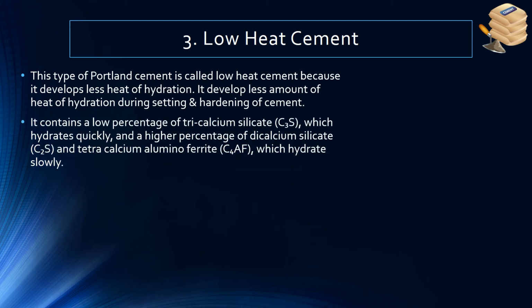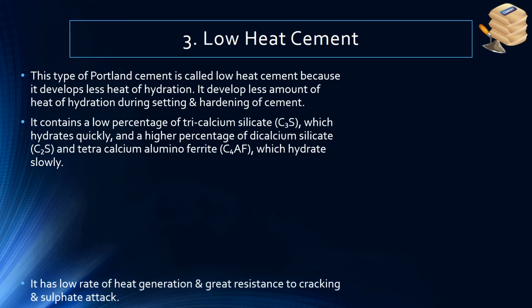It contains low percentage of tricalcium silicate which hydrates quickly and higher percentage of dicalcium silicate and tetracalcium aluminoferrate which hydrate slowly. The compounds which are responsible for early strength of cement are used in less amount and those responsible for slow heat of hydration of cement are used in a more quantity.